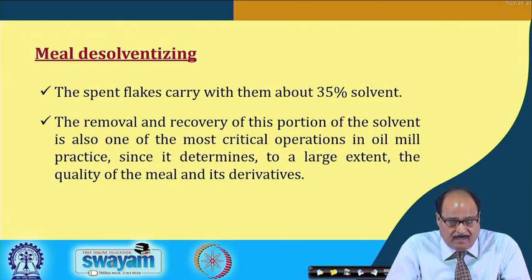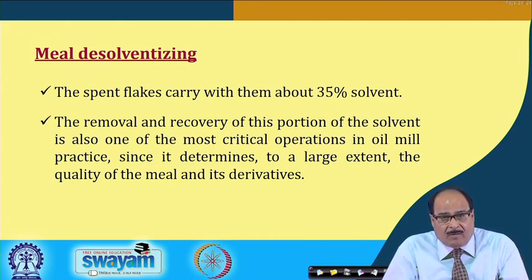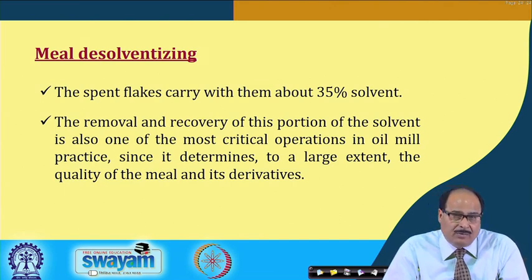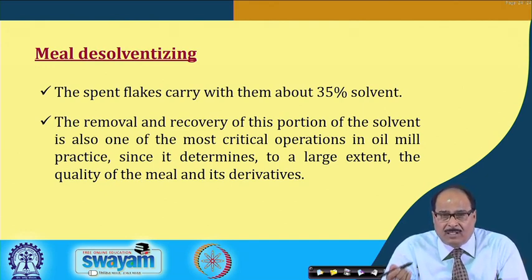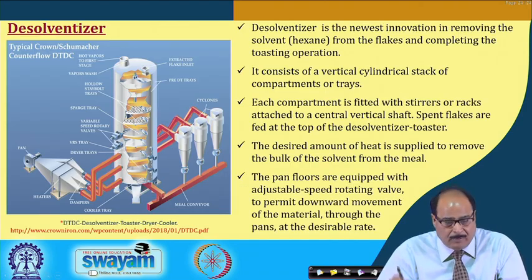Okay. A good meal desolventizing step will ensure better recovery of the oil, almost full recovery of the oil, because the meal which is obtained should have no oil residue, and at the same time the heat treatment given for the meal desolventizing should not adversely affect the protein quality, or result in excessive protein denaturation. It should not disturb its PDI or NSI values.